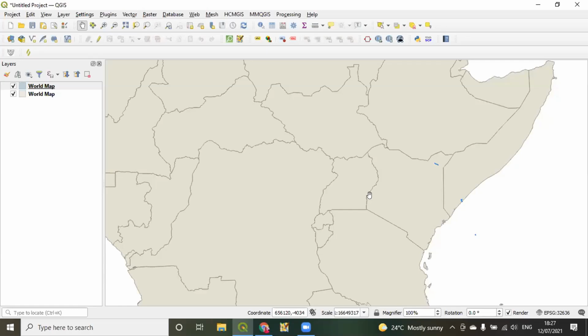So depending on the project requirements, you'll have to choose any. I think it's okay whichever you prefer to use. Me, I can use any, especially now for demonstrations. For now, Rehema is using WGS 84, which I think is okay. But if you still want to use ARC 1960 UTM 36 North, it's also, I think, absolutely fine.